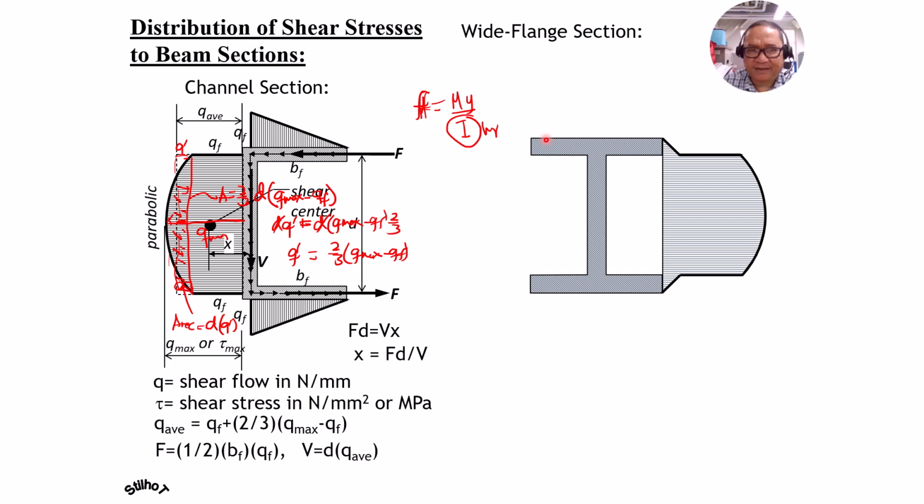Then we have here an abrupt rise in shear stress or shear flow because the denominator of the formula VQ over IB is the width of the flange first, just above the junction. It is the width of the flange, which is greater. Then for this abrupt increase in shear stress, the width used there is the width of the web. So that's why it rises rapidly.